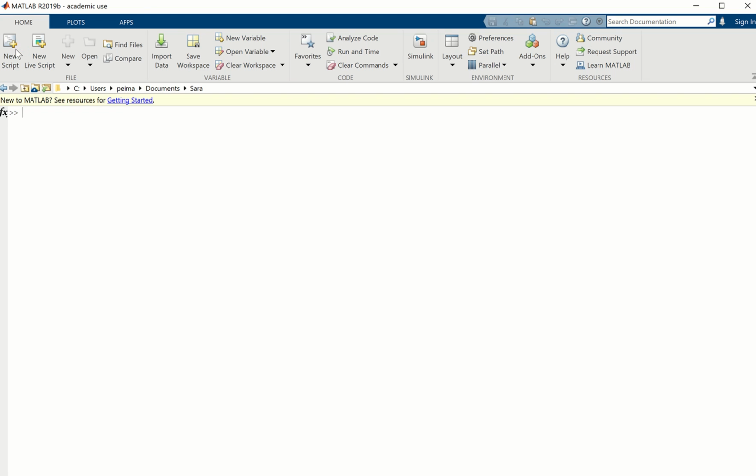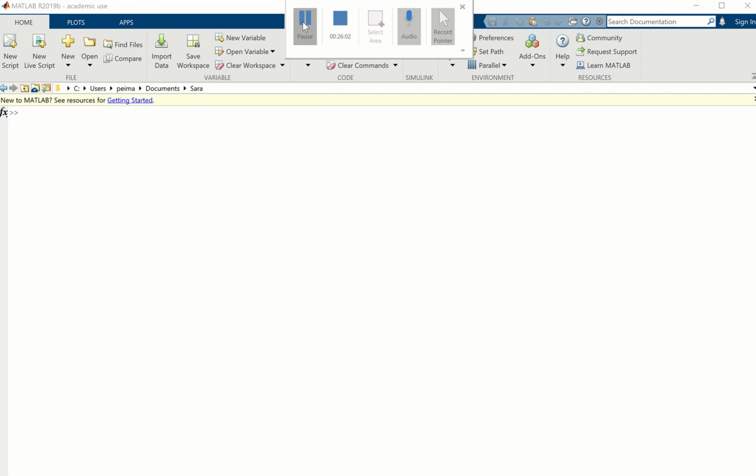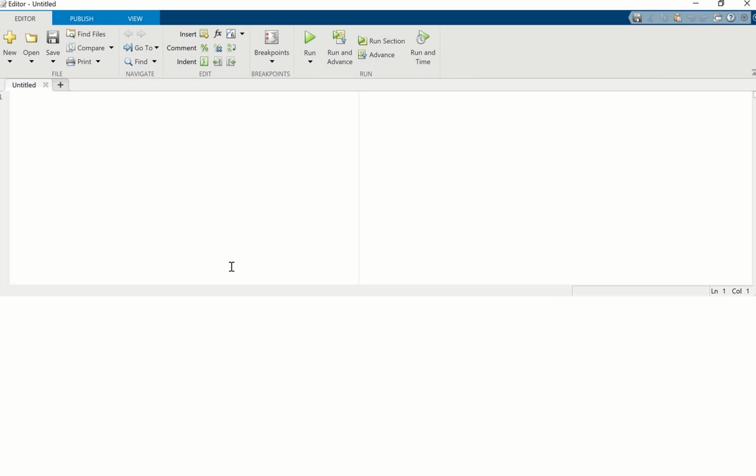First of all, I have to generate an M file. Okay, so I'm going to go step by step for this MIMO system. I'm going to write the function dm equals MIMO system of t and m, where m is the state variables.